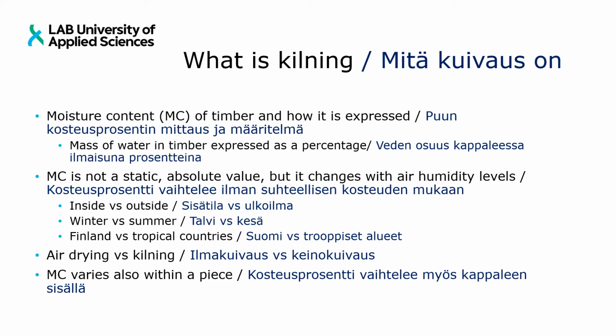What is important to remember is that moisture content is not a static absolute value which remains always the same once the goods have been kilned, because it changes with the humidity in the air. For instance, inside versus outside, winter, summer, and Finland and tropical countries.